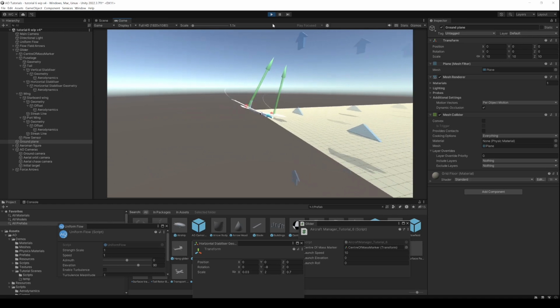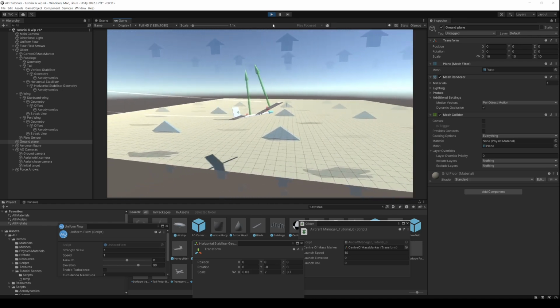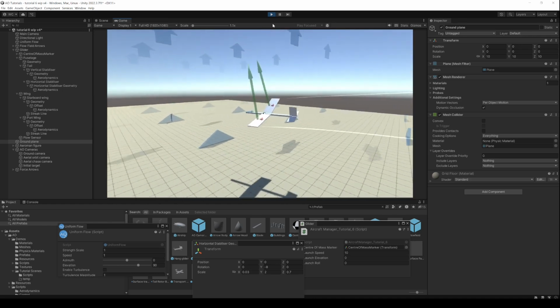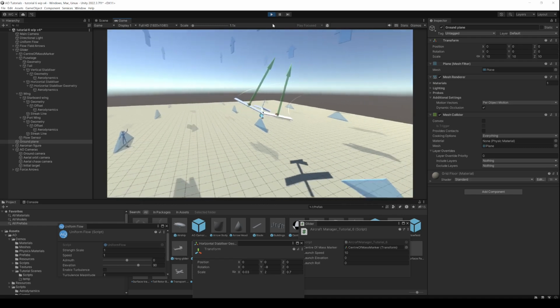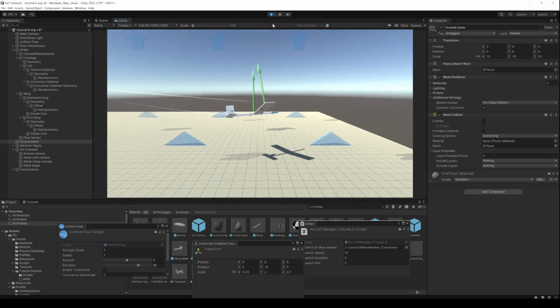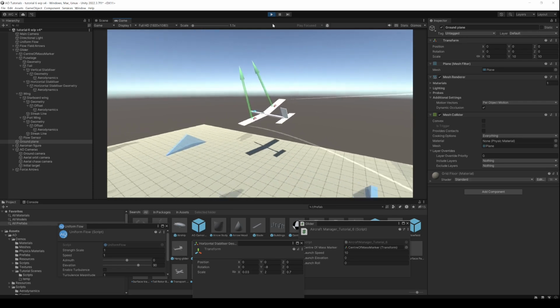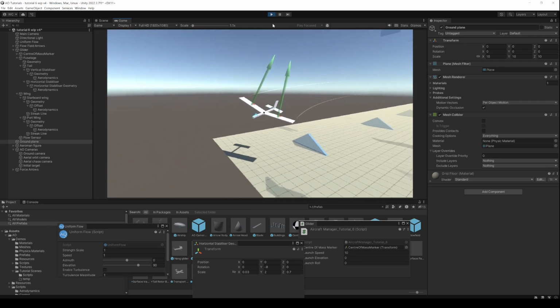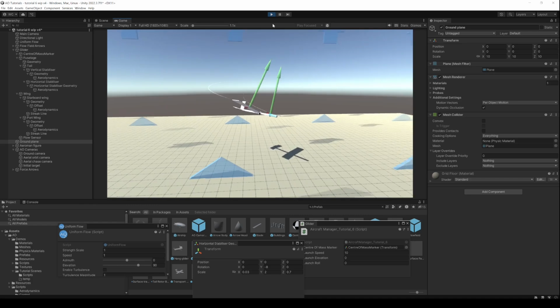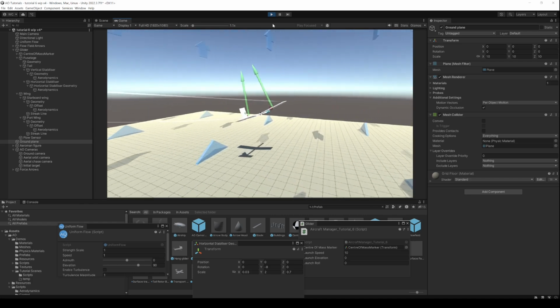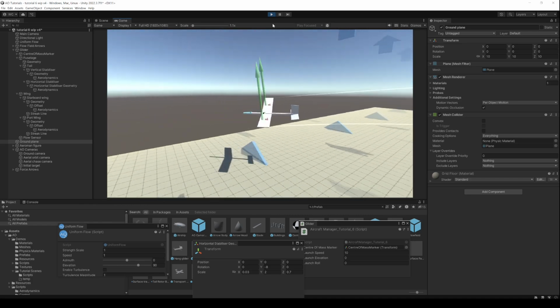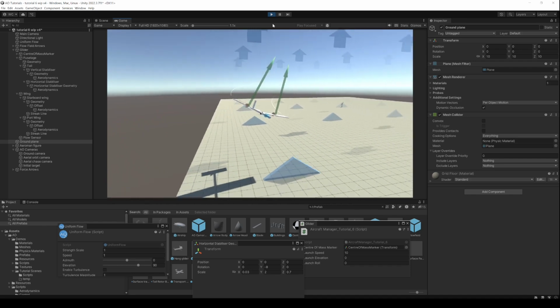There are no flight control systems in there, that's just pure aerodynamics and geometry. It's because we've got a bit of dihedral on the wing, and we've offset the vertical stabilizer. The plane is always just flying slightly sideways, and that's making it go in a circle. And because we've got the deflection of the horizontal surface, that means it's balanced at positive lift as well.